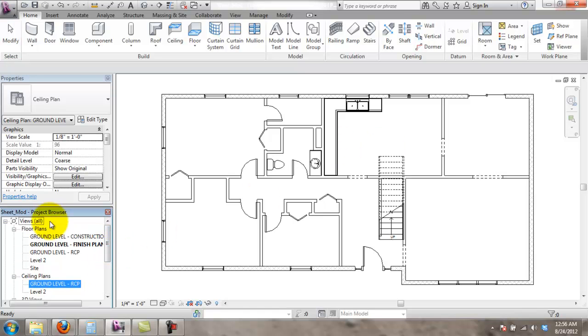Let's see. So on my ground level here, on the construction plan, what I'm going to do is just kind of give this some rough dimensions. We haven't really talked about permanent dimensions, so I'm just going to go through and give some of my raw dimensions. I might miss a few here, but the idea when you dimension these interior walls, basically, and you'll cover this in Condocs, you want to portray to the builder, obviously, how to build the space, but you don't want to overdo it with dimensions, and you definitely don't want to duplicate dimensions, because when you duplicate dimensions, that means you have the ability for one to be, let's say, X and one to be Y.